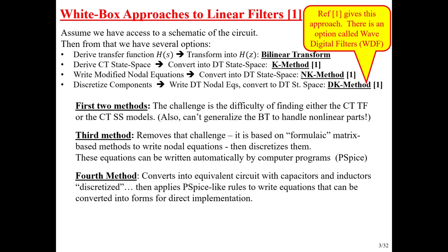So the idea is, instead of focusing on the circuit as a whole and coming up with a state space model, we can basically come up with models for just capacitors and inductors that we can discretize to capture the dynamics of those directly.